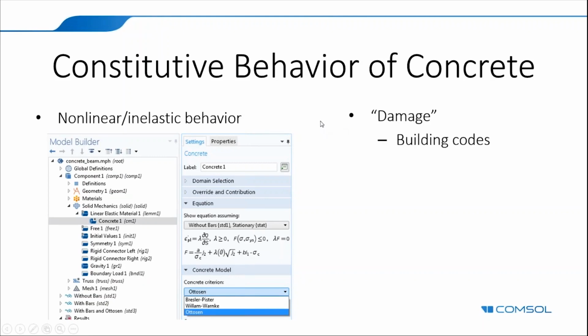Now, sometimes you have building codes that specify the material stiffness, the elastic modulus you should use, as a function of time. This is because if you don't have a fundamental mechanistic model, but you have done experiments and you have seen how your strength varies with time. So when it's setting, your strength could be increasing with time, but later on, it could be decreasing or getting damaged. So the simplified models just give you this as a function of time.